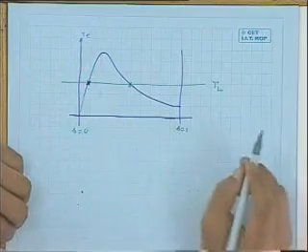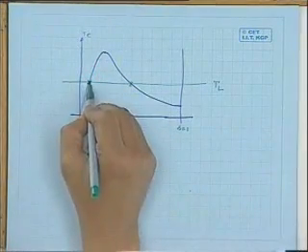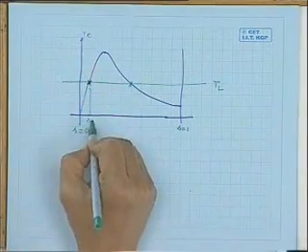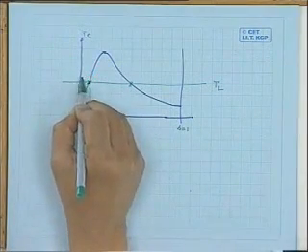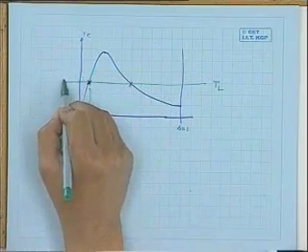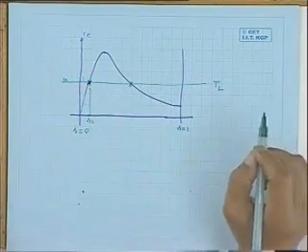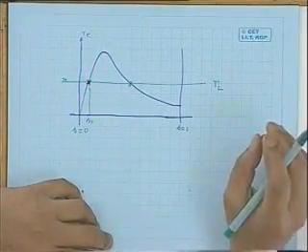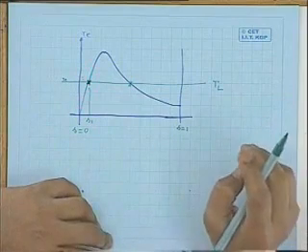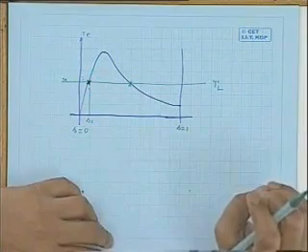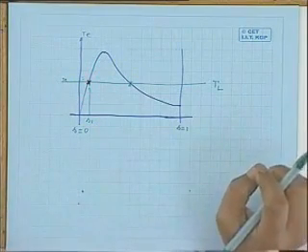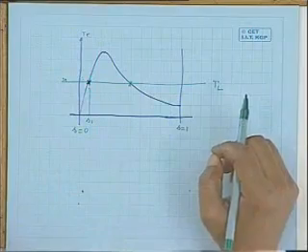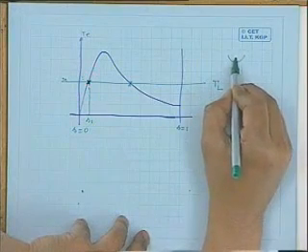Now, as we have seen, let us consider this point of operation. Why is it called a stable operating point? Suppose the machine is operating steadily at this slip S1, developing this much torque TL. Now, as you know, to test the stability of any physical system, what you have to do? You give a slight disturbance to that point and see whether it comes back to the original steady state operating point on its own. Then it is a steady state, stable point.